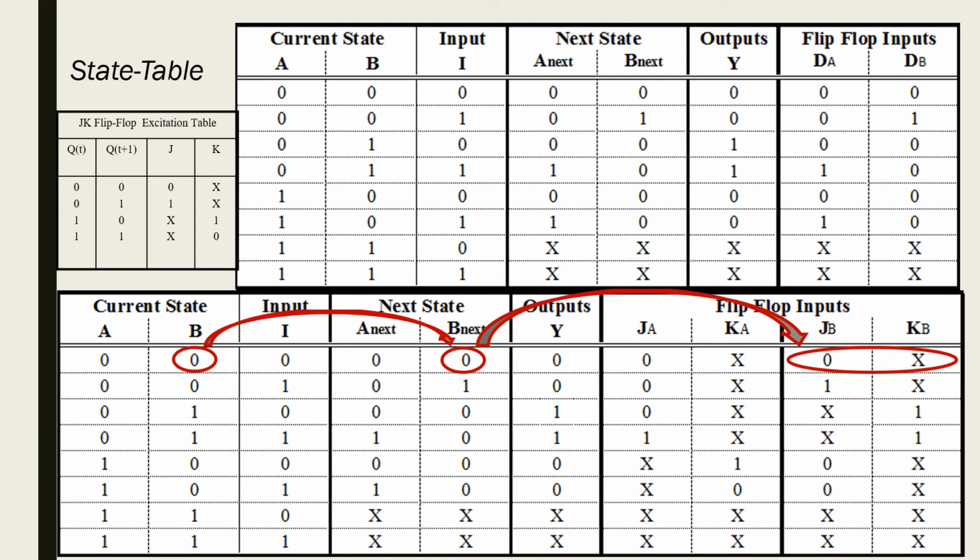So this slide here gives you an idea of what's going on and how to solve the problem. For sequential circuits, we have two types of problem, as I mentioned before. One problem is when the next state is unknown and you are going to use the characteristic table, and the other problem is if the JK or D or whatever are unknown, and you can use the excitation table to solve the problem. And I'll show you now. This slide gives you most of the problems you're going to face to solve any sequential circuits.